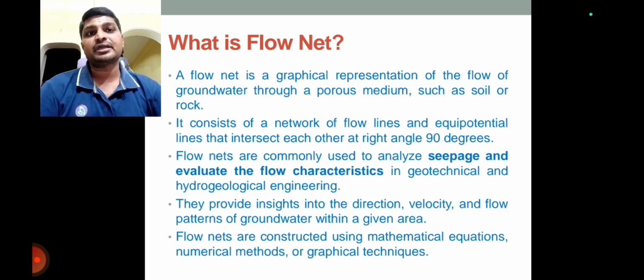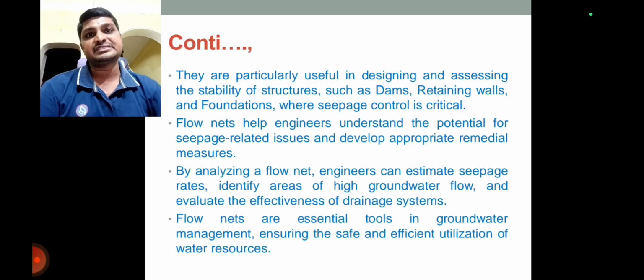Flow nets are constructed using mathematical equations, numerical methods, or graphical techniques. They are particularly useful in designing and assessing the stability of structures such as dams, retaining walls, foundations, bridges, and earth dams where seepage control is critical.